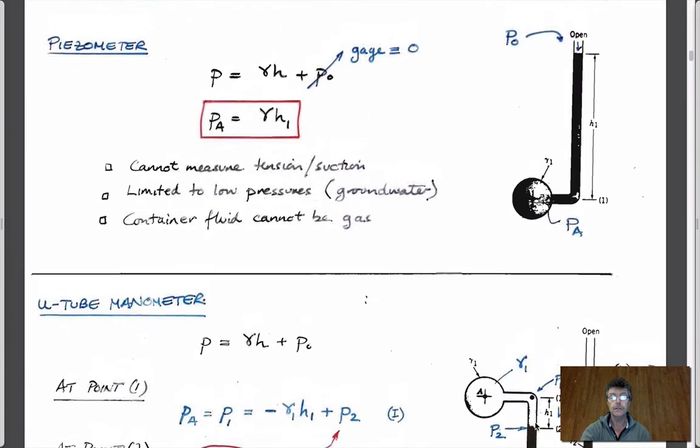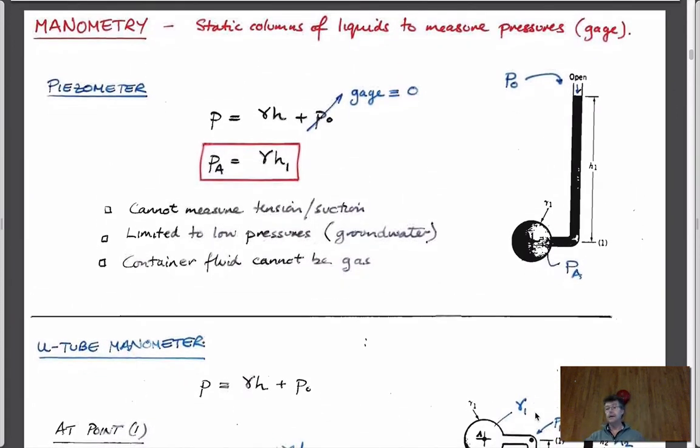So, in terms of big concepts, we made a big deal about manometer equations, and we've done some examples with those. Of course, you realize that manometer equations are actually just Bernoulli's equation with the velocity terms dropped out. So you remember that if you take Bernoulli, you probably don't need to make this into a class, do I? But we've been adding these layers of complication, I guess, to what we do. But if the velocities are 0, as they would be in a static fluid, then we lose both of these terms. And then we can look at the differences in pressures as you go up and down.